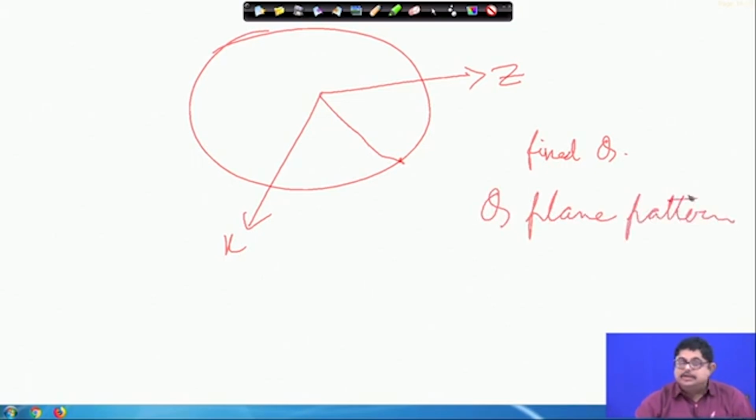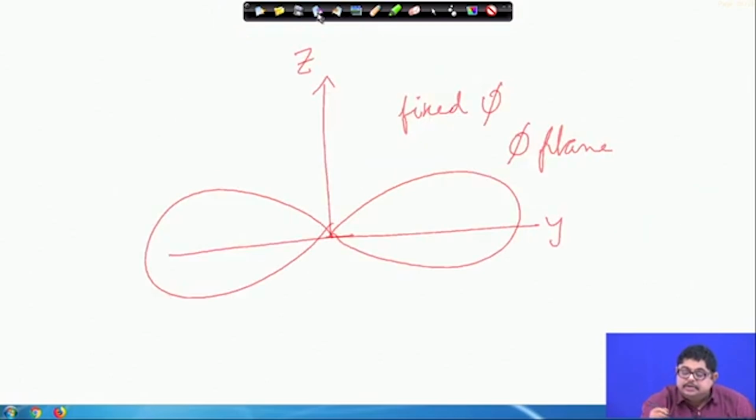So, power patterns of antennas are like this. It shows that in the azimuthal plane a current element does not have any variation, it behaves like an omnidirectional antenna, but in a phi plane it behaves like a dumbbell. So, in this direction it is giving more power than another direction, and at the current element line or axis it is having no radiation.